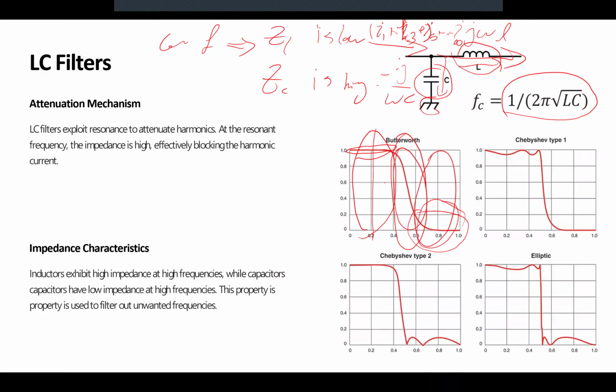Normally they put it closer than 60 than 180, so it's around 100 hertz. They make sure that all the harmonics fall over the cutoff frequency, so they are damped significantly. But our fundamental, we let it go with minimum damp. This is ideal. What you see here, the gain factor is 1, meaning no damp.